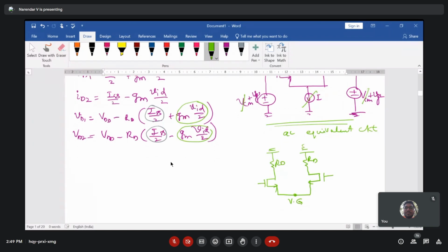Okay. And here we are applying the AC signal. So we indicate only the AC signal here. This is our AC signal, and here we also indicate the AC signal. This is your VG2, and this is referred to be your VG1. Okay. And definitely here we have VD1 and here VD2 AC components, not DC component. And the difference of these two, again AC differential component, which is positive. So here it is negative and this is positive, VOD differential AC output, right? So this point is referred to be virtual ground.